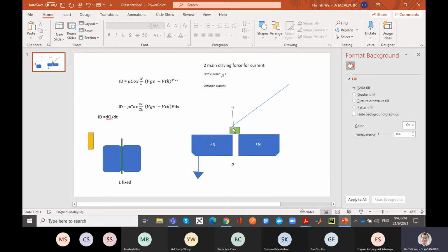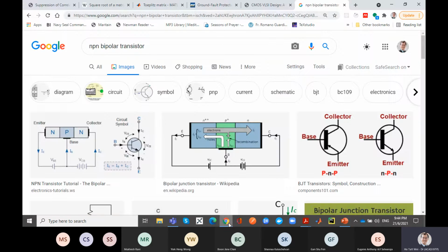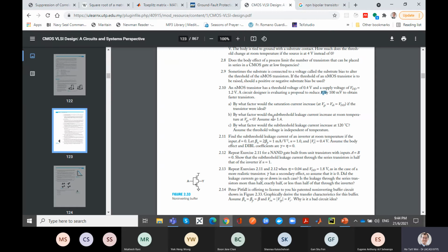There's a capacitive coupling: this voltage is capacitively coupled to the base of this NPN transistor, and therefore any slight change in VG, non-zero, even much smaller than VTH, because you don't have a conducting channel here, is actually inducing leakage current. We use the NPN bipolar transistor to estimate how much is the leakage current of the MOSFET. So that is the question you are trying to address here.